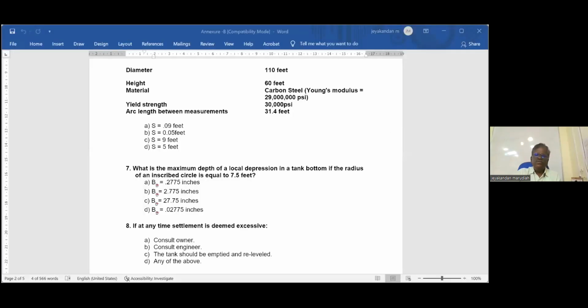Yes, there is no need to remove insulation everywhere. Where can we use LRUT? For example, underground piping we can use, cross-country pipeline we can use. It is following the guided wave. Guided wave is called Lamb waves in ultrasonics. Those waves we are using. That's why guided wave testing, LRUT, they are using low frequency. Generally, normal UT we are using high frequency.